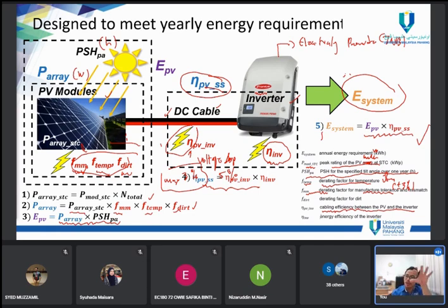For grid connected, we are not going to put any storage batteries. The storage batteries are not included in the design of grid connected. It only applies to the standalone PV system. We have only inverter and PV modules for the grid connected PV system. So embedding storage battery with solar panels is not cost effective.